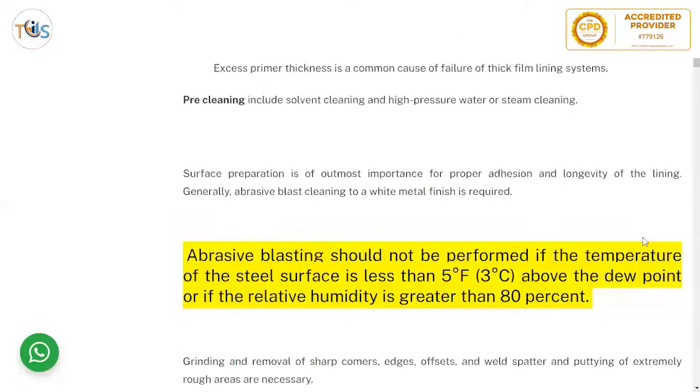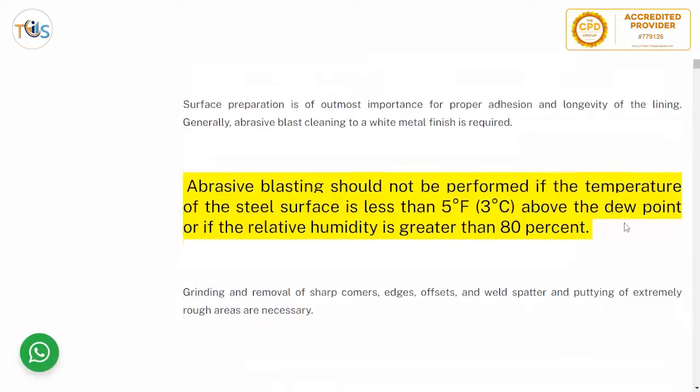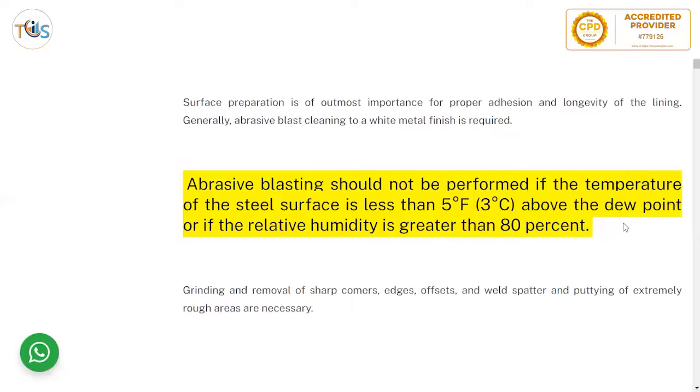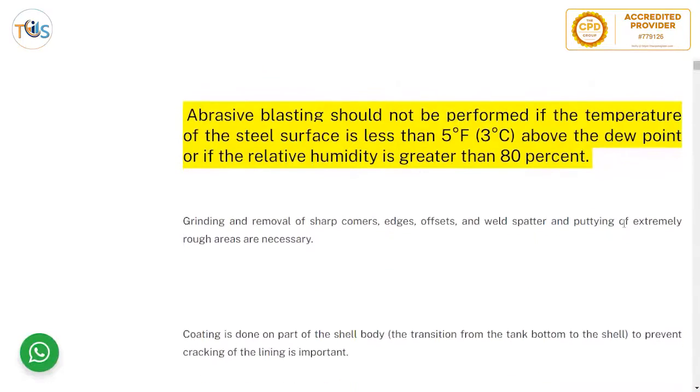Cleaning methods include solvent cleaning and high-pressure water or steam cleaning. Surface preparation is of utmost importance for proper adhesion and longevity of the lining. Generally, abrasive blast cleaning to a white metal finish is required.